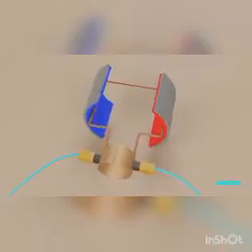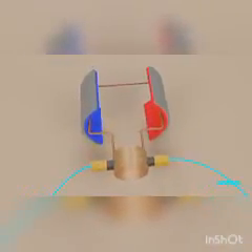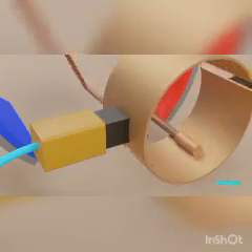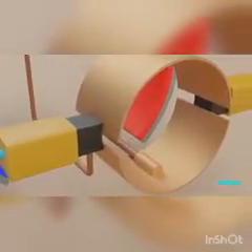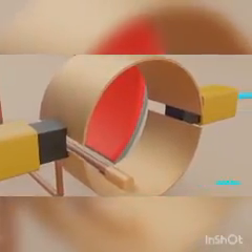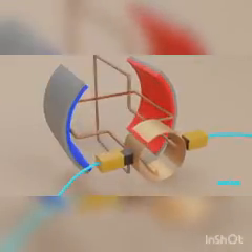Now so far we've only used 1 loop on the armature. This will cause our motor to have an irregular speed, and in fact, we could get stuck in this position, with the brushes halfway between commutator segments. What we can do is split the commutator ring and then add another loop.